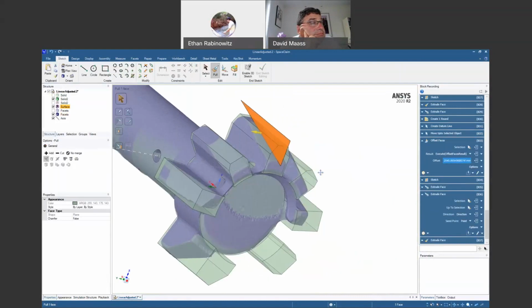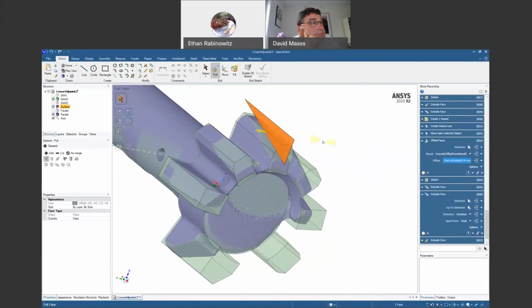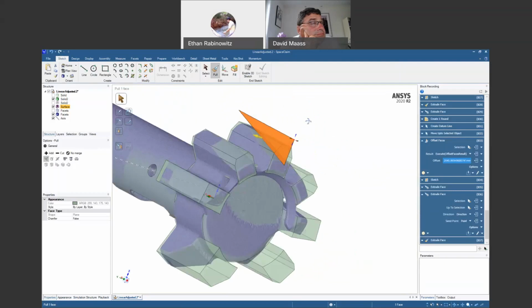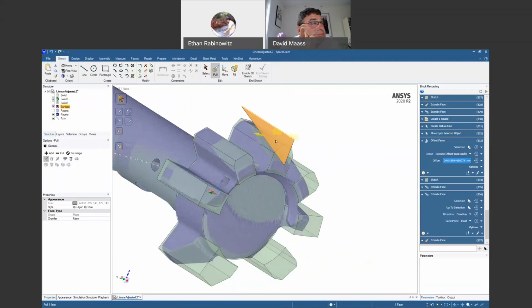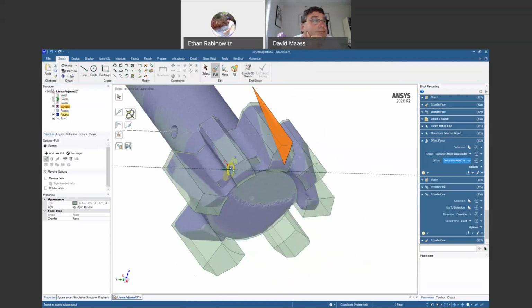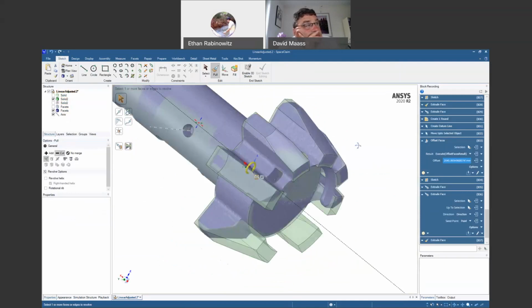All right, we're going to do a few things with this piece before we turn it into a solid. Since, if this was just one cut all the way around, I would just say revolve, grab our axis, make sure that cut is turned on. And if we want to see what that looks like, we could do it and see here.